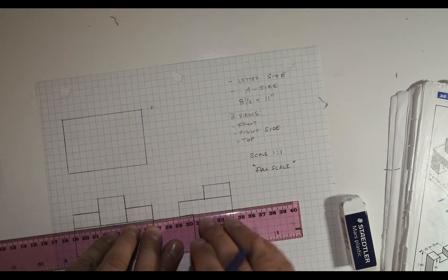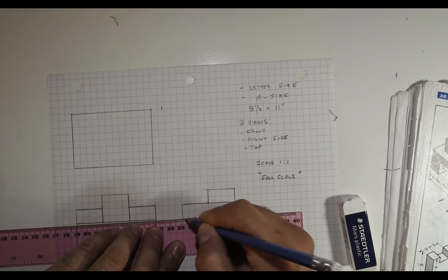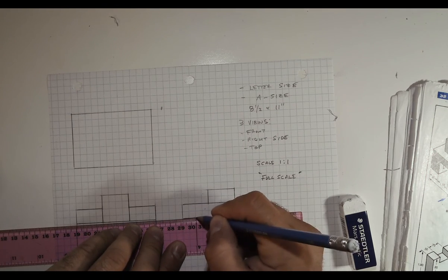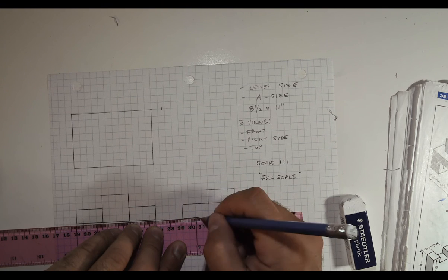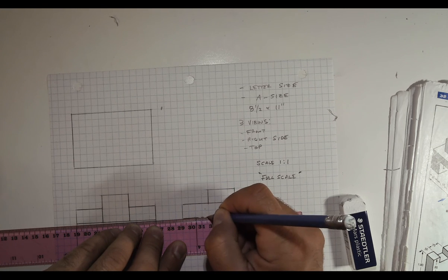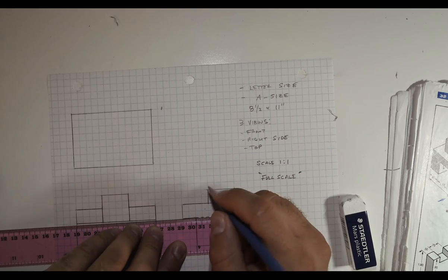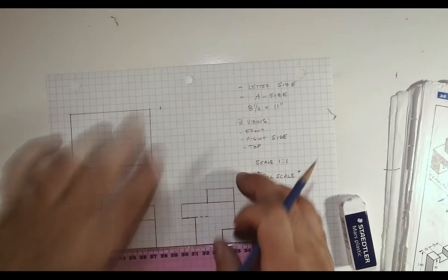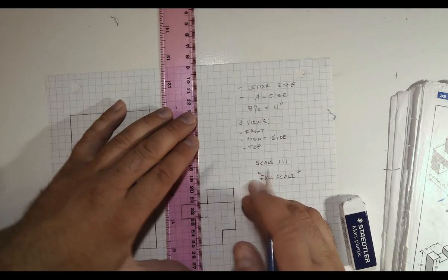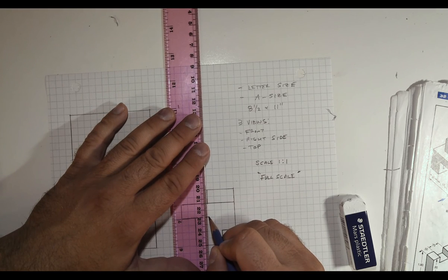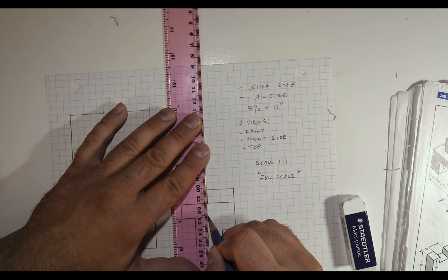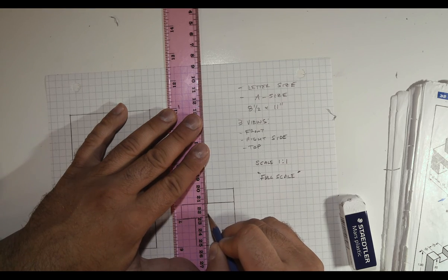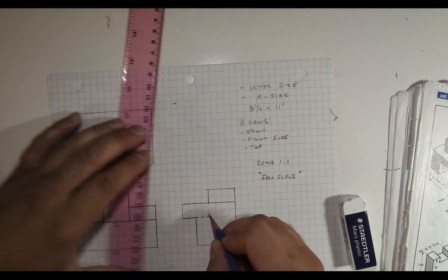Now what you want to do with the hidden lines is when you start a hidden line, the first dash should terminate with the adjacent visible lines, so that there's no ambiguity of where the feature starts and stops. Also, when I have two hidden line edges meeting, or multiple hidden line edges meeting, I want to terminate those dashes like so.